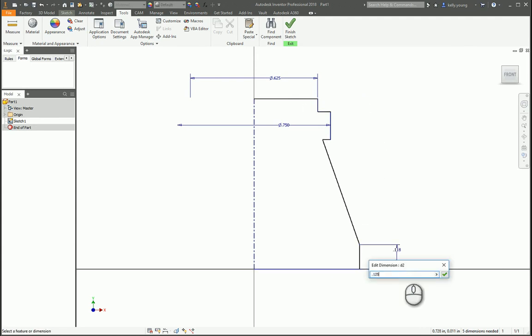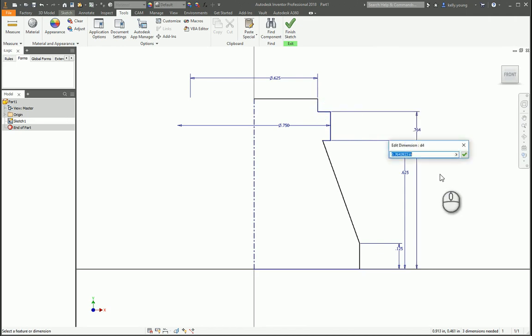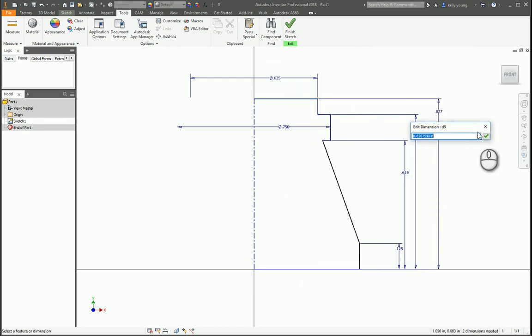Now, depending on where you're dimensioning it from, you can go to here. It's usually good practice to use a single baseline, so that way you can control the overall distance from a point. If you're doing inspection dimensions, you can retrieve these later. Rather than just doing a dimension from here, you can go up to there, so you don't have a tiny dimension here.